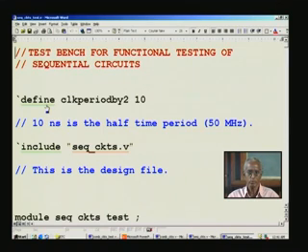But what do we do in the simulation environment? You have to create it once again by the Verilog coding itself. In order to facilitate this, we first define what is called clock period by 2. This is the name that I have given. If you feel it is too long, you can give any other precise name. All this is like a C program, where you can give meaningful names, right. And what we say is this is the unit of time.